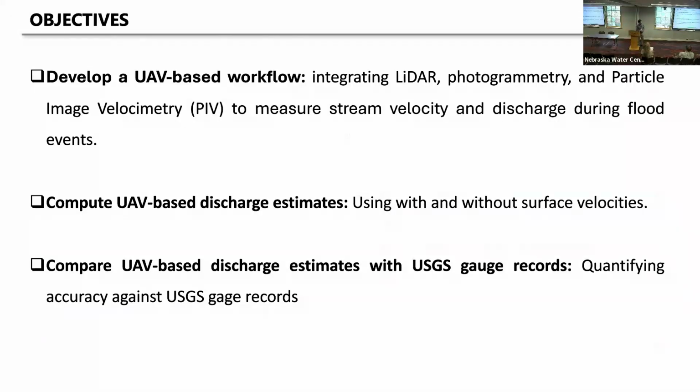So we want to develop a UAV-based workflow that integrates LiDAR, photogrammetry, and particle image velocimetry, called PIV. We are going to measure the stream velocity and discharge during flood events.